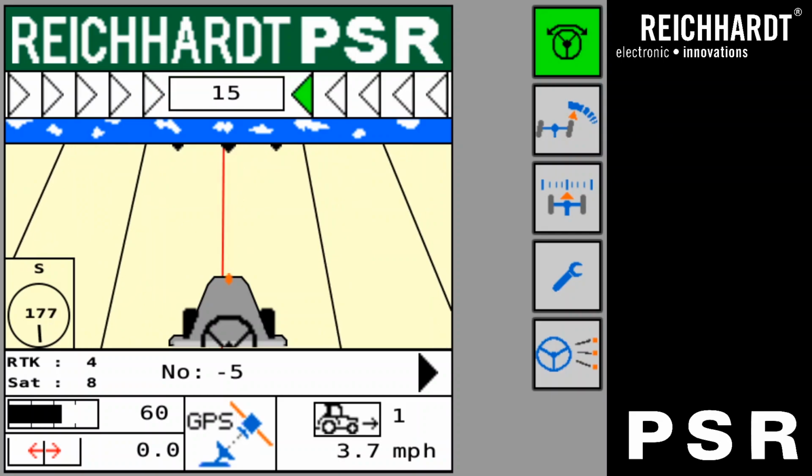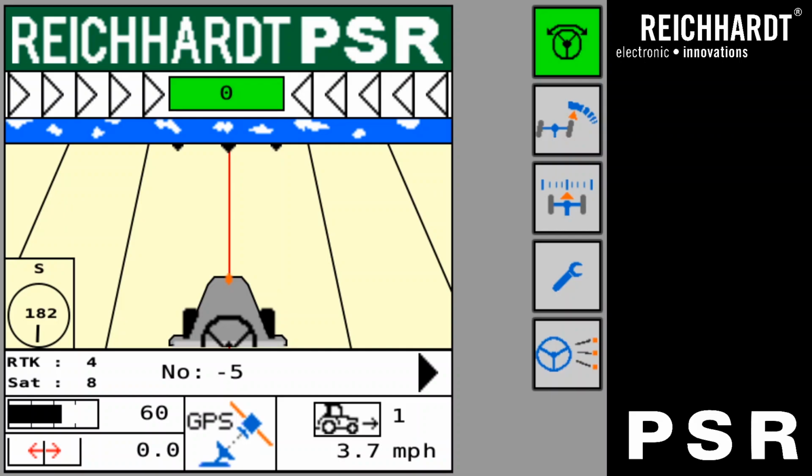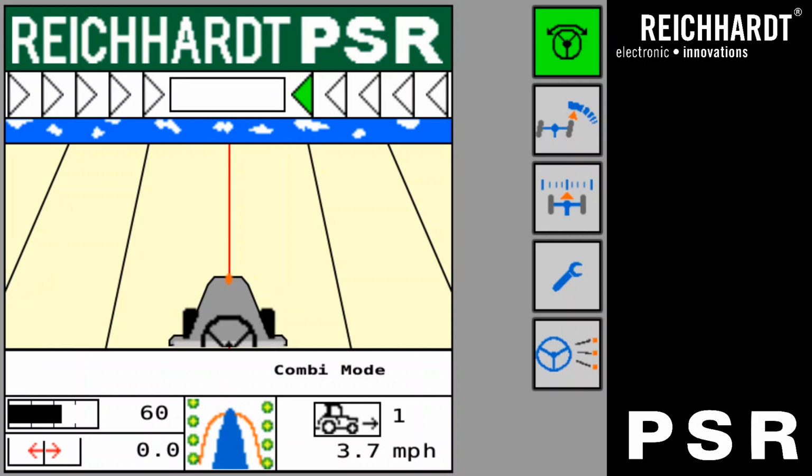Let's see if I can get it going here right. Not very good at steering here with my simulator. There we go. And once it's guided GPS on the line over X distance, it'll automatically switch back to row guidance. So as you can see, it stayed engaged and now it's guiding off of sensors. So now that we've traveled another distance, we're going south again. I'm going to go ahead and disengage the auto steer.